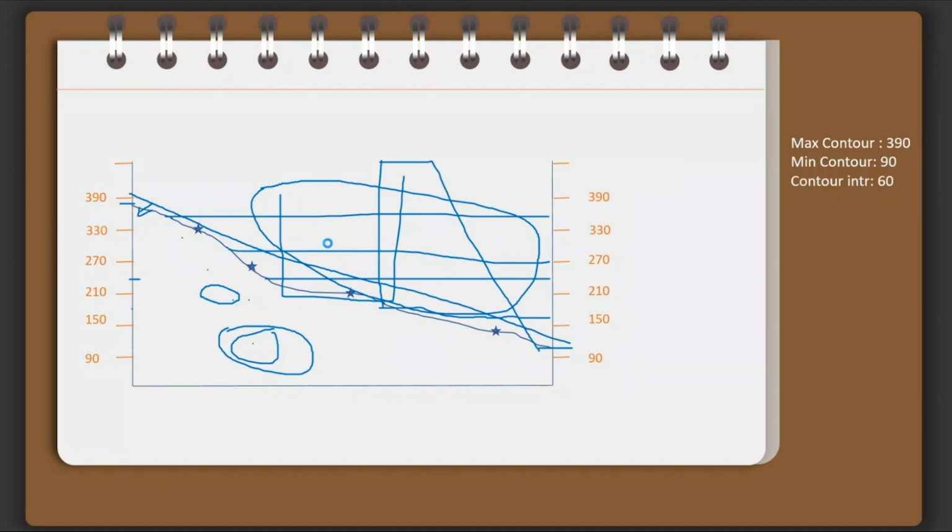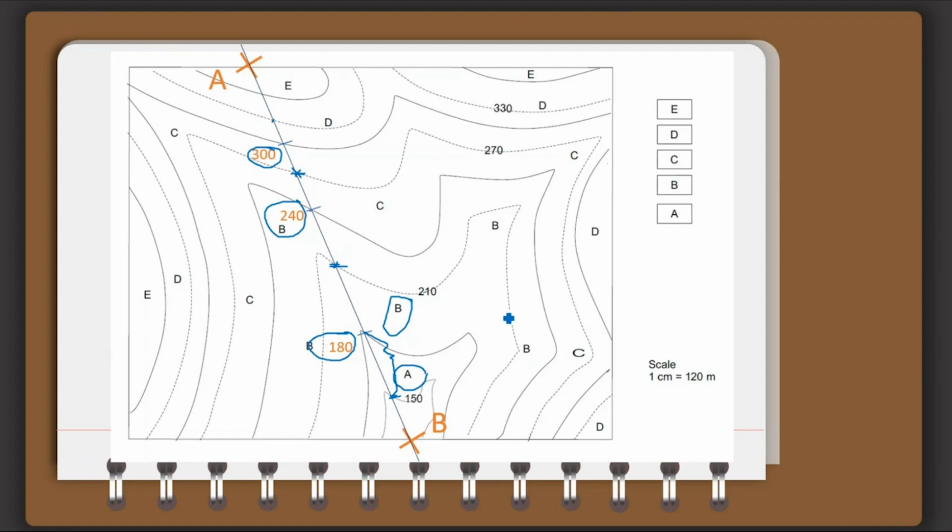So similar geological cross-sections may be prepared for a number of sections like we have created here. Similarly, I can create another cross-section this way, so that will give the slope and the characteristics of this region in this way. And you can go for a section this way also. If you prepare a number of sections, then I'll come to know the actual characteristics of the rock types, where it is sloping, where the layers are increasing or decreasing, all the characteristics of that region I'll be able to interpret from these geological map studies.